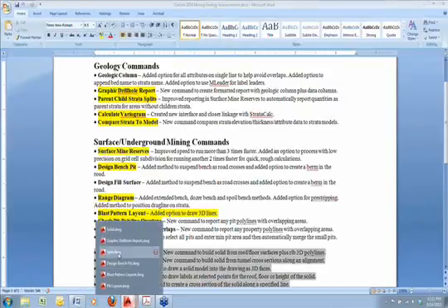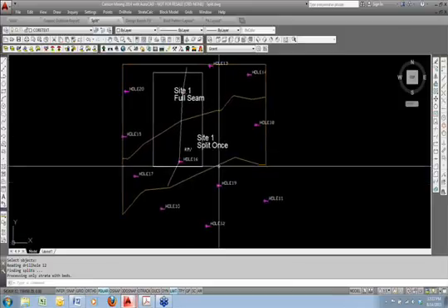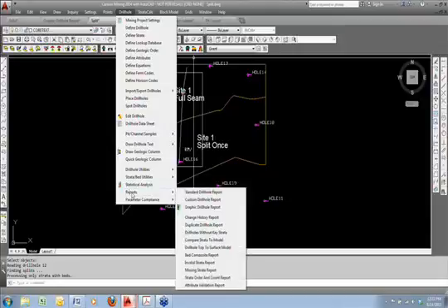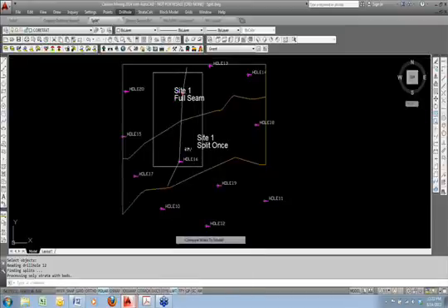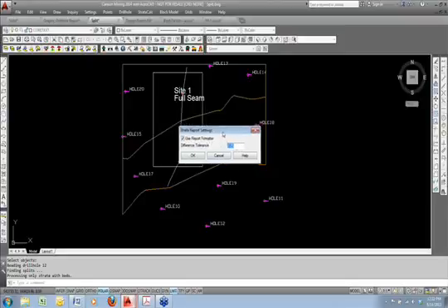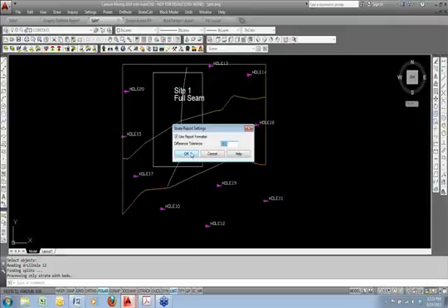And so I'll go ahead and use that same drawing since it has drill holes and surfaces already created. This one is also in the drill hole reports section. We'll go down to drill hole reports, and it's the new command, compare strata to model. And you give it a tolerance. So I'll use the report formatter to export it out to Excel as an example, but we'll give it a tolerance of, say, 0.25. This will be feet or meters. And it could be thickness, it could be elevation, it could be any chemistry attribute that you're comparing.